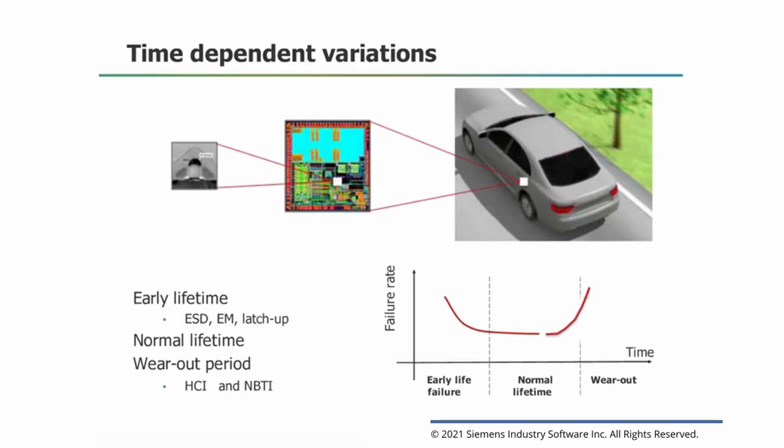Consequently, they degrade transistor drive current, circuit speed, noise margin, and matching properties, which eventually will lead to partial or complete failure. So to seriously take these effects into account, they must be thoroughly modeled and considered at the design stage. Before we start to analyze the possible remedies of this problem, let's have a brief review of the physical effects.